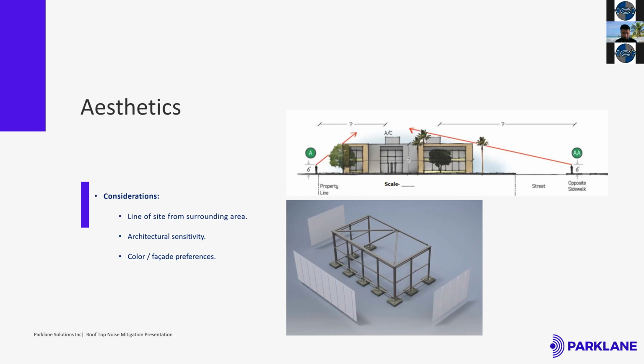No. As long as we have the manufacturer's serial number or model number, we could get that from their website. They typically would have, for each model, their sound, exhaust, intake, and radiated noises. While we can get that information, really the acoustic consultant is the one who would typically stipulate, based on this bylaw, it needs to be X dB at this property line. That's something you would have to actually measure to see whether it complies or not.